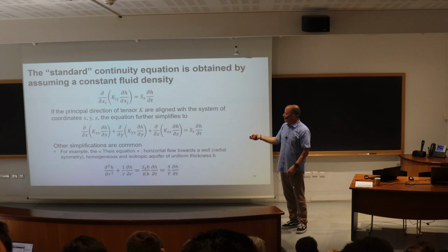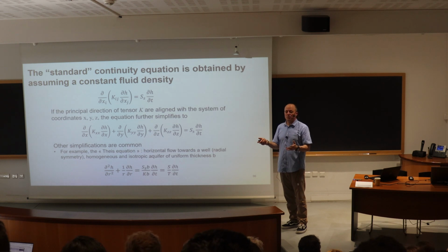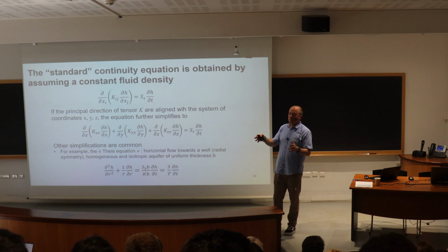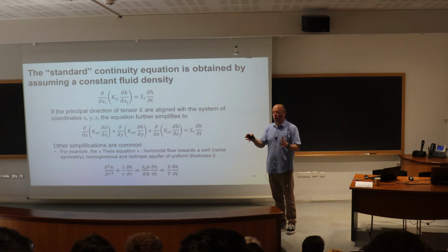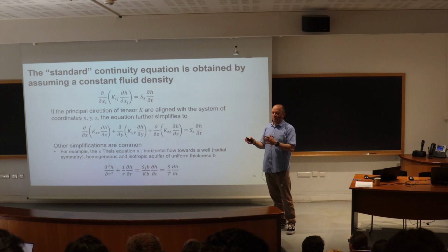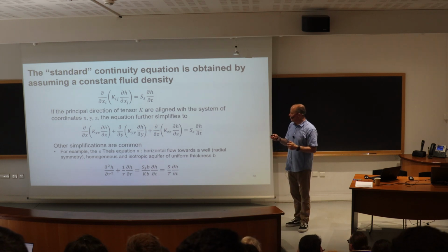So these terms could be taken out of the derivative, and you might end up with the Laplace equation, a very simple equation. And that's basically what you do when you do graphical resolution of the groundwater flow equation by drawing a flow net in 2 dimensions: you're solving the Laplace equation, a partial differential equation with lots of simplifications, but you're still solving an equation that is based on the principle of mass balance.